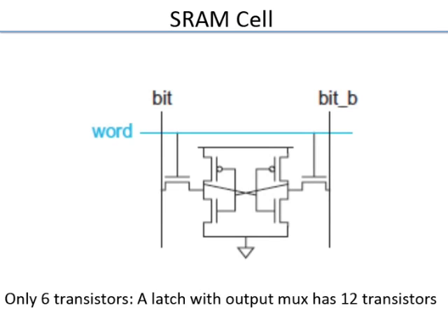So now when you look at this latch, we said that we can optimize the latch by removing these two inverters, that inverter in the output and perhaps an inverter in the input. So that's kind of what is done in some sense, but you see it's done in a kind of funny way out here. Basically, this is what a modern SRAM cell looks like.